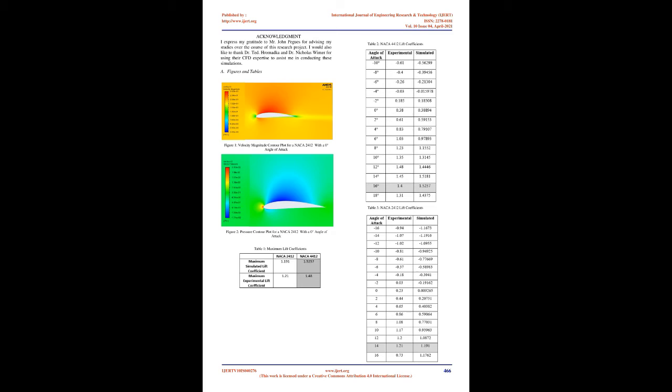C. Verification. Verification is a valuable step in CFD that determines if the implementation of the governing equations is correct. Results can be verified by comparing results with analytic results or other simulations. The comparison in verifying the data will be comparing the pressure coefficient plot in the pre-stall region with another study and with expected trends. The pressure coefficient plot demonstrates consistency with the plot obtained in [6].